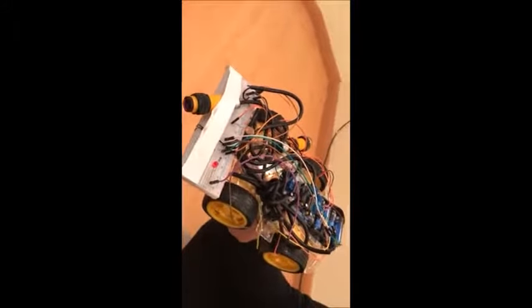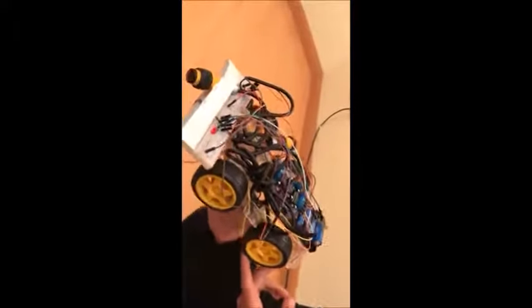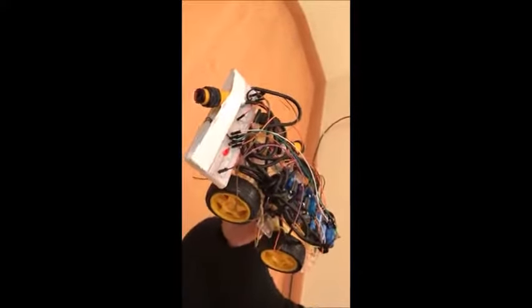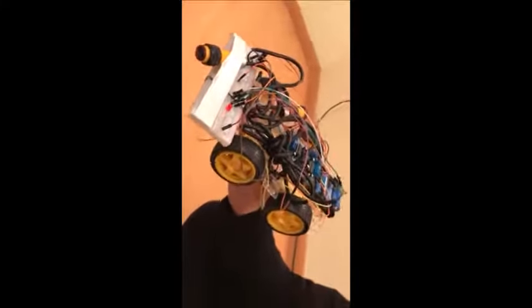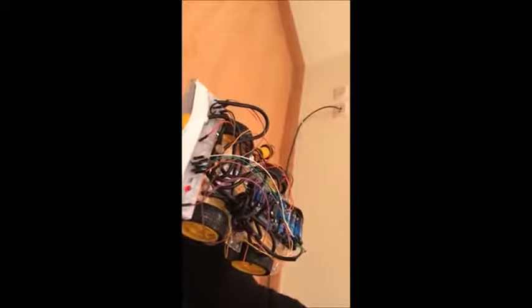The motor shield can operate up to 4 motors by connecting each positive and negative edge of each motor to the motor shield, which are here. Each pin of the motor shield is connected to the positive and negative. Initially 2 DC motors run forwardly and the other 2 backwardly. These run forward and these 2 run backward to initiate the motion, causing the car to move forward in a straight line. As 2 of the 4 motors are placed in the opposite direction, if an obstacle is detected from here from the IR, the other 2 forwardly will change direction to go backwards and then move forward to avoid the obstacle.